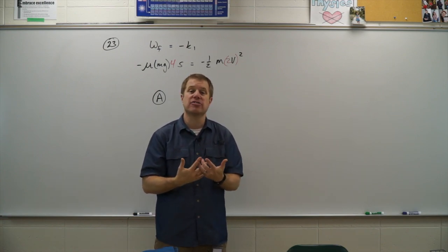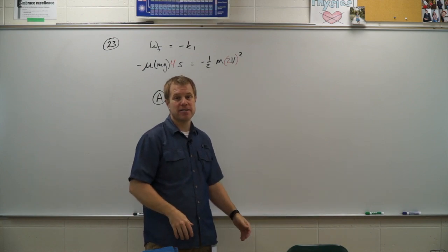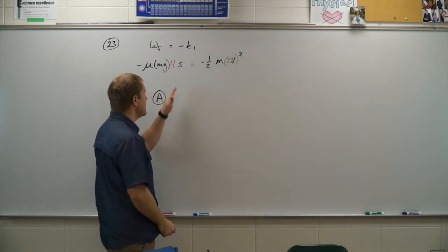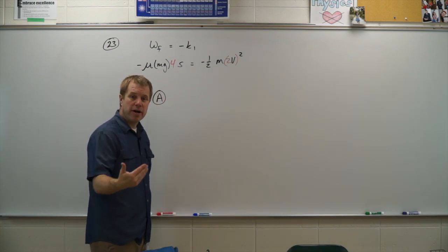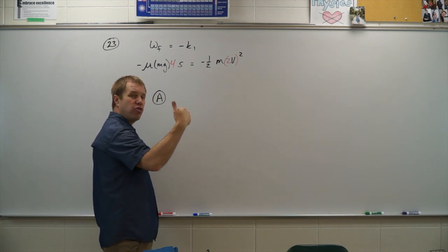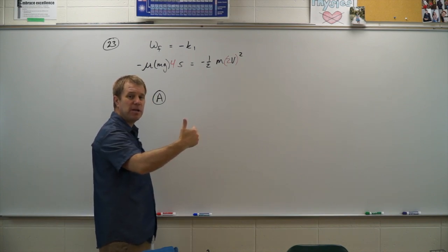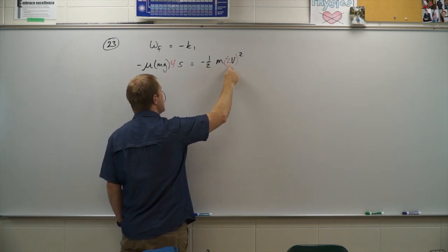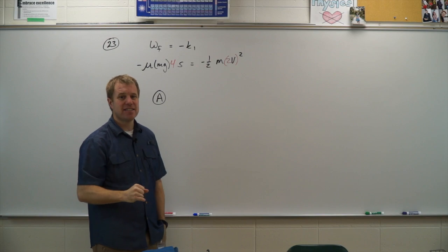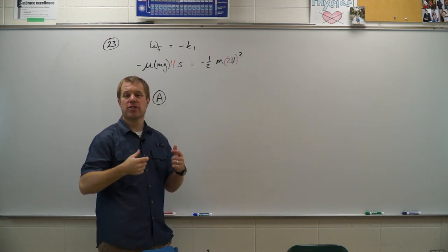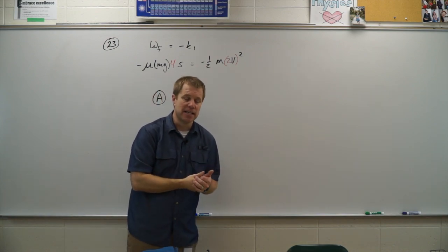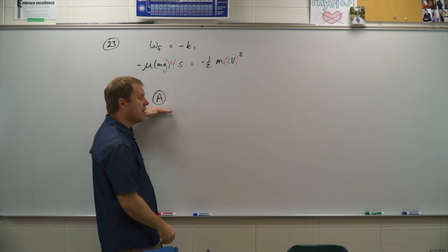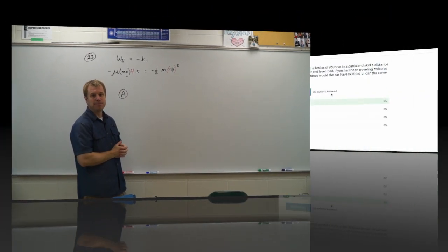So if you're moving faster, you're also traveling a further distance while you react. So that distance is actually larger. That's why in a school zone, instead of going 30 miles an hour, a little bit over the speed limit, you're supposed to pull it back to 15. Half that speed is going to be a quarter that distance. You're going to stop faster. You're also not going to travel as far while you're reacting. So good idea there. Correct answer, A.